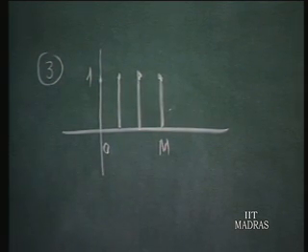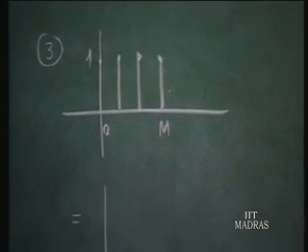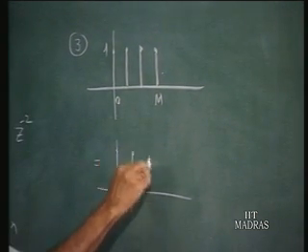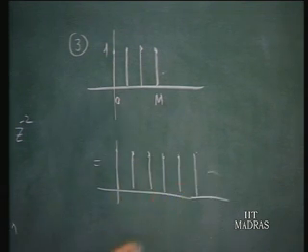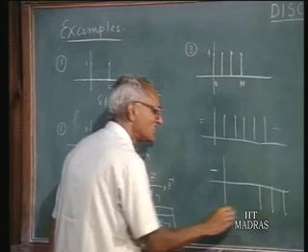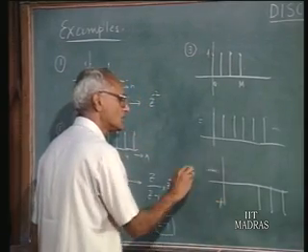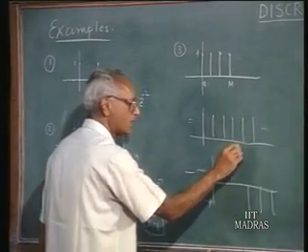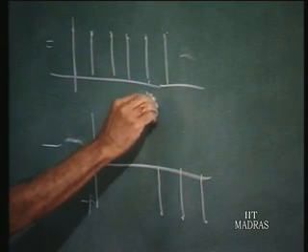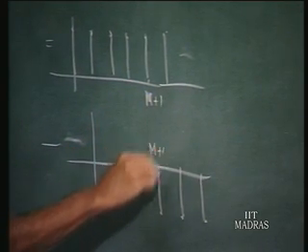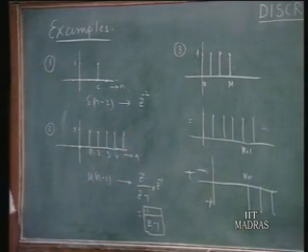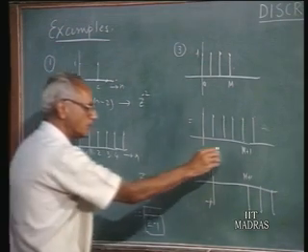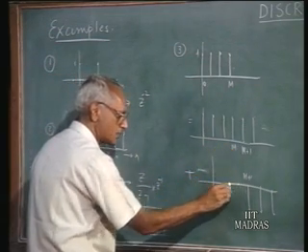Now this can be written as unit samples right through minus a function which has minus 1 value from, say, this, suppose you want up to m, therefore if you take m plus 1 onwards, this has minus 1 value. So if you add these two functions, then you get this. So up to m the value is 1, and beyond that it is 0.